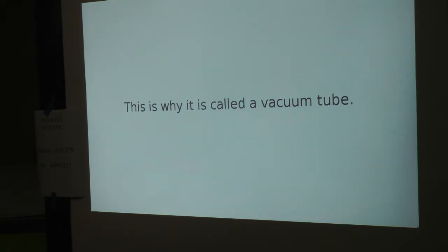Okay. And can I just add one quick thing there? When you look at a new tube, you see this burnt spot that's actually shiny. And that's called the gettering spot. What that is, is a little pellet of magnesium. After they've got the vacuum, they warm the tube up and that burns any air or gas or anything that's in there to make a really good vacuum, and it causes a shiny spot on the tube. I'll show you that at the break time, because with one tube you can see all these bits, and once you've seen it, you can remember it. But it's very hard just with words, I'll be honest.